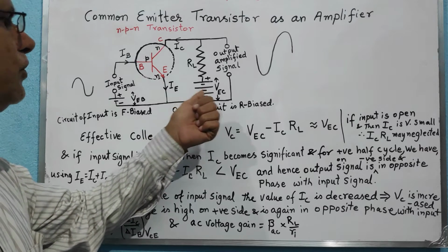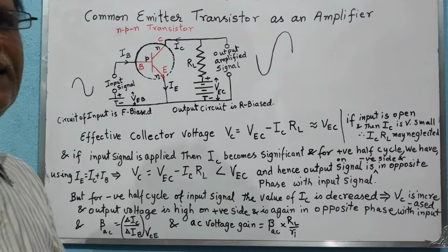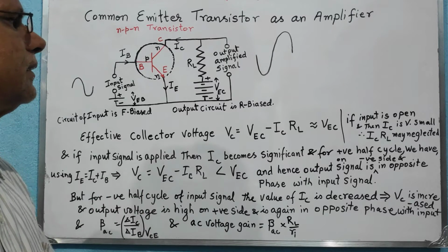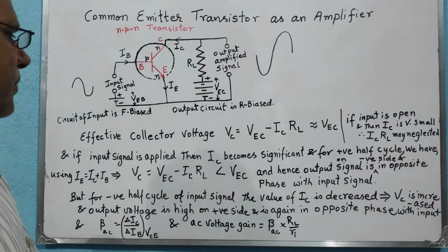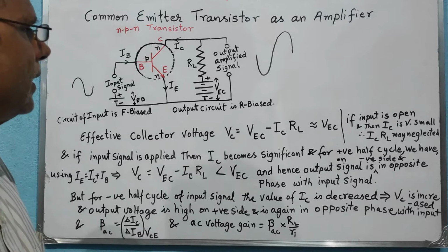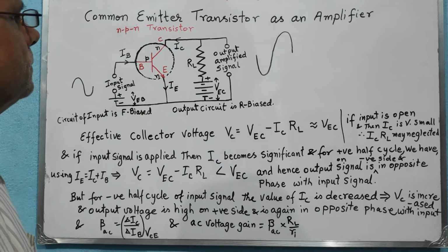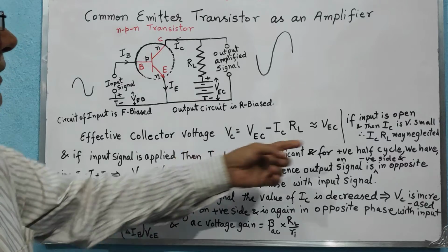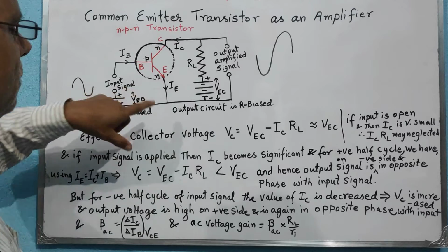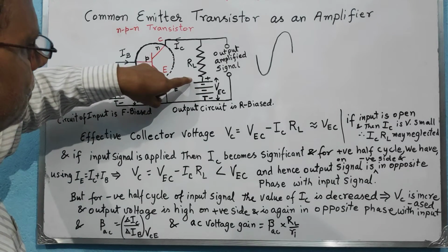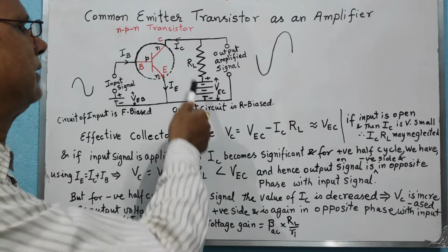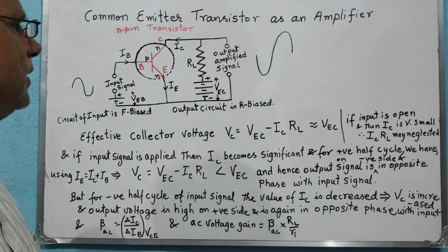It will be only due to the reverse bias effect, and the current in the reverse bias case, unless it is at the breakdown voltage, is very negligible. Therefore the potential drop across the collector will be nearly equal to the applied reverse bias voltage EC, the potential given by this battery combination which is providing the reverse biasing of the output circuit.